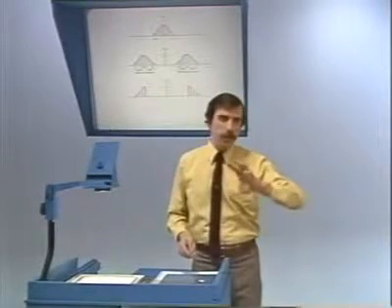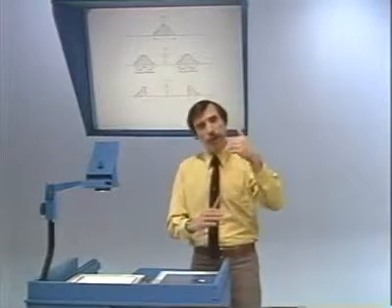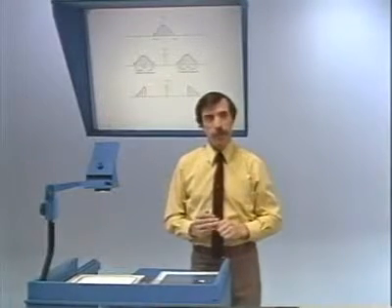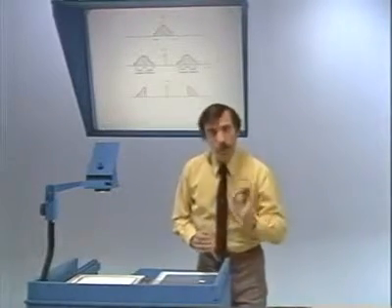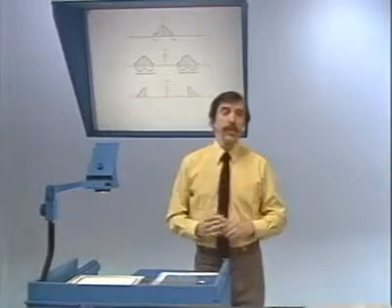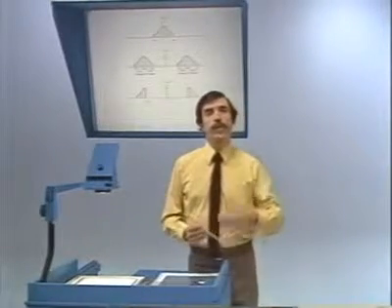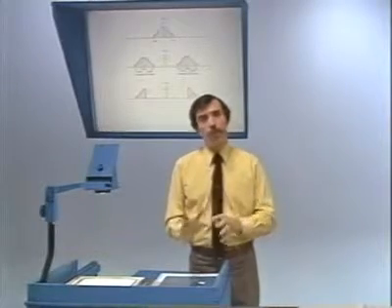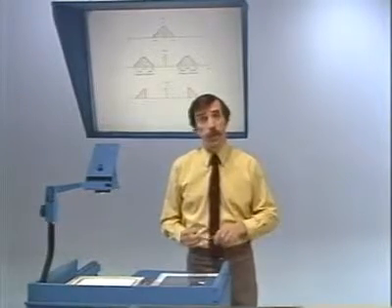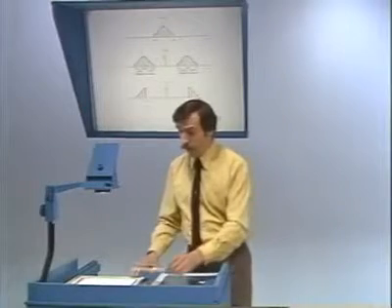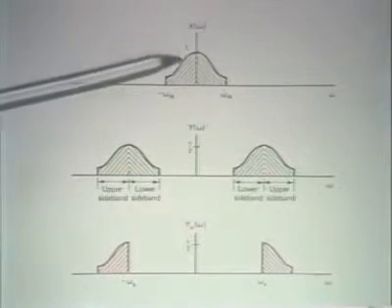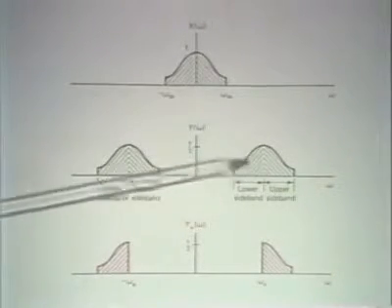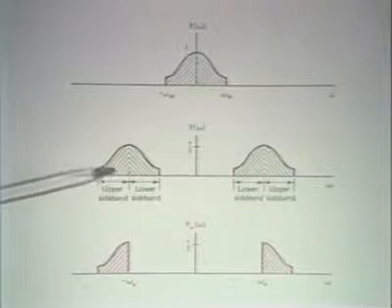And the issue there really is that now you've got to transmit both a real part and an imaginary part. So what you can ask is, if you still want to transmit a real valued signal, how can you somehow remove the inefficiency or redundancy in the spectrum? Well, notice that we have this spectrum moved here and moved here.